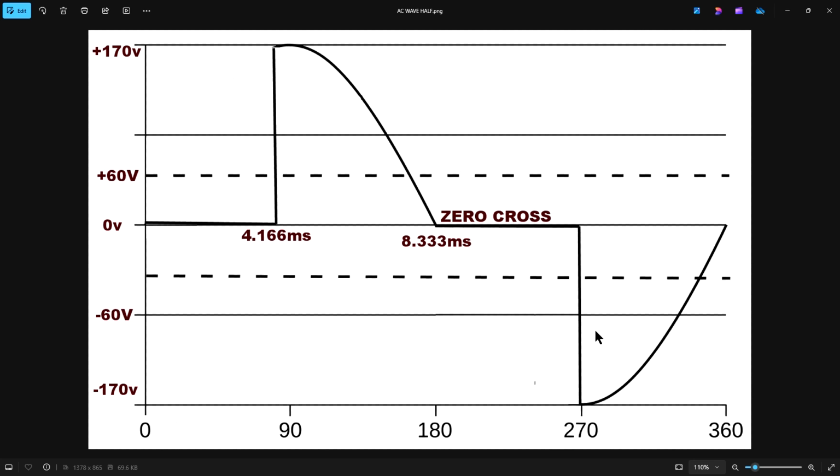And if I was doing this, for example, if this is supposed to be 50%, basically when my 0 cross circuitry pulsed my CPU and said, okay, you're at 0 cross, I would start counting, and I would count 4.166 milliseconds, and then I would send the pulse to my Triac to turn my power on, and that's how I would get half my power. So let's move along.